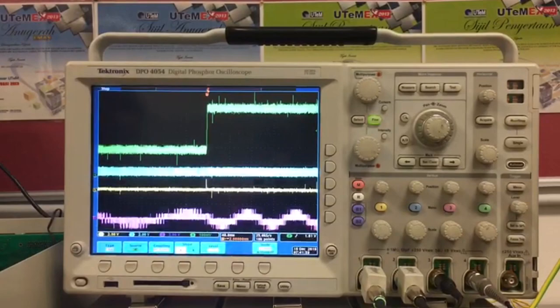The second and third lines represent the error torque signal after and before passing through the hysteresis comparator. The last line represents the D-frame voltage of the induction motor, which is similar to a sine wave.